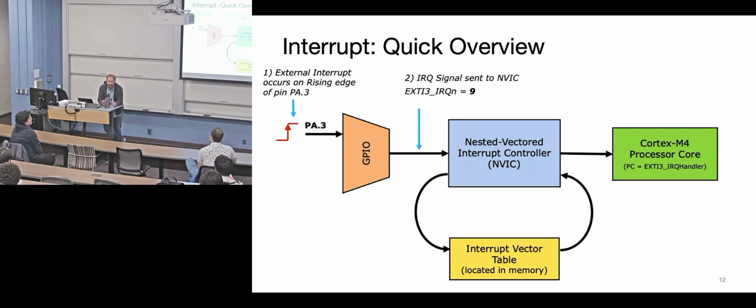Why can't all of ARM have one stack pointer? Yeah. Isn't it that you have a different number of interrupts for implementation, and so you don't know how often they use it? Everything you said was true, except it doesn't affect the stack pointer. So why don't we just set the stack pointer to be FFFFF for everything? Every ARM Cortex M4 that comes out, that's the stack pointer by default.